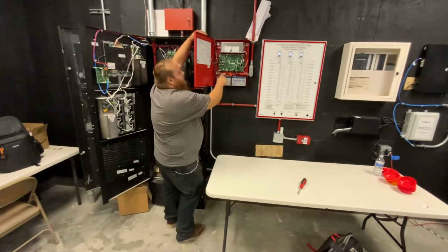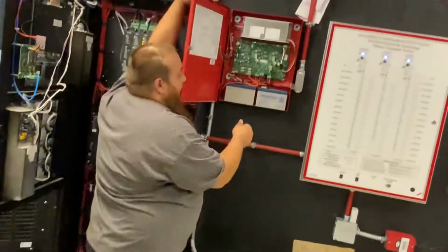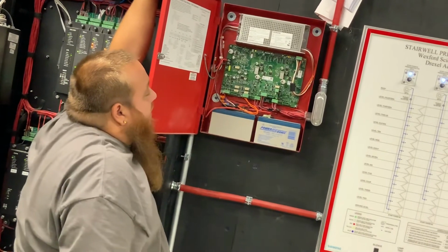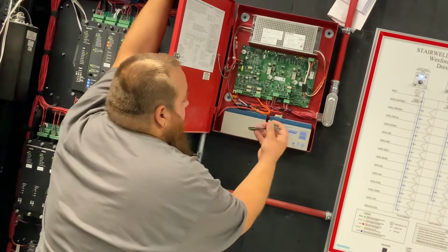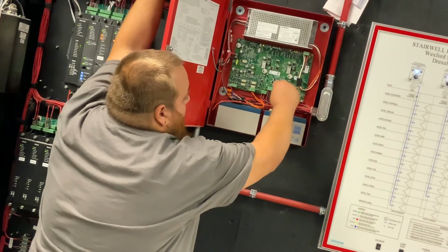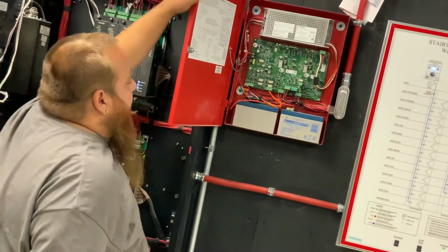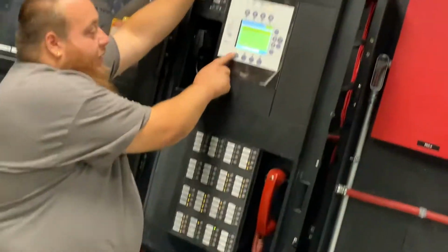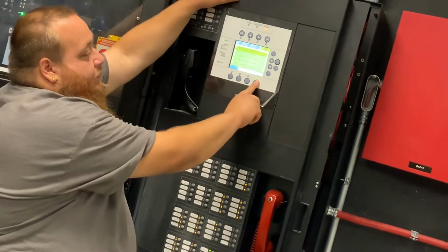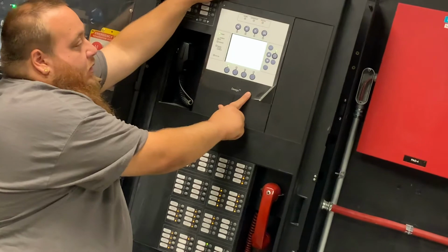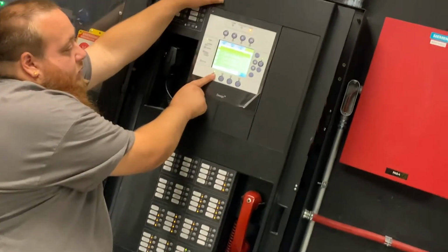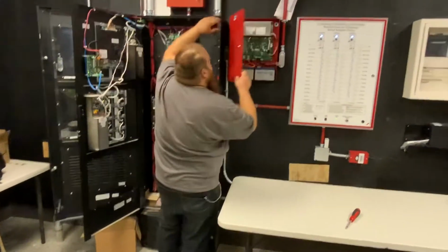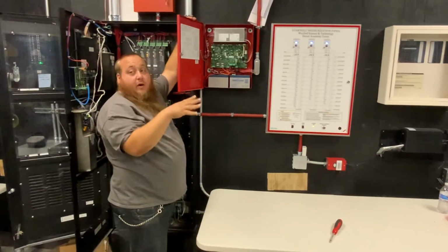You look closely, now you notice those lights are blinking. And say if the issue does fix itself, it'll self-clear. Put this back in. Now that that is all back to normal, change the state, the system will let you know. Now see trouble's out, reset. Now it's disappeared. Also with these, when they're being activated, those 4 lights will also glow as well.